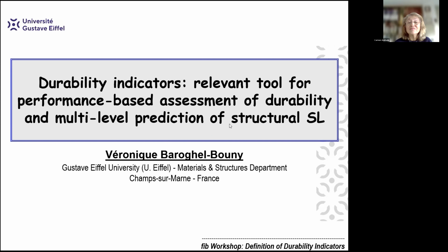For example, the model will provide a chloride concentration profile, and you need to measure this monitoring parameter, which is the chloride profile, in field condition or in lab condition, depending on what you include in the model.